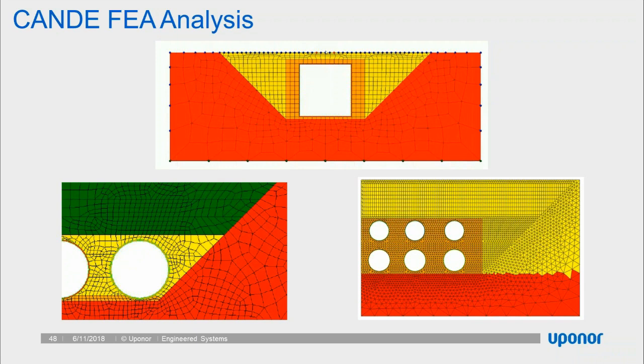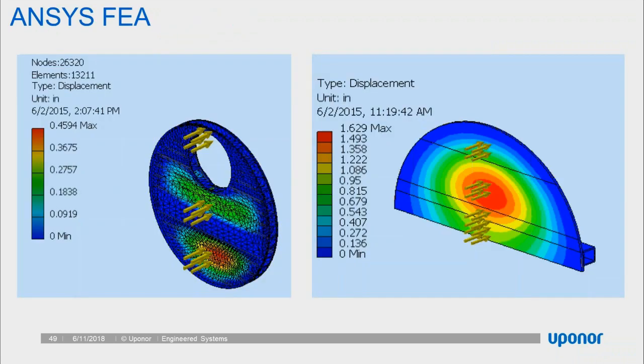Essentially, it allows us to build up the structural element in the model, the subgrade, the non-select backfill zone and the critical backfill zone, and then apply our vehicular loading or live loading over top of the structure to determine deflection. So this is an important tool when the ability of PPI Chapter 6 and Spangler's formula to correctly model the structure is limited. We would go to a CANDE FEA analysis to confirm deflection and performance of the system.